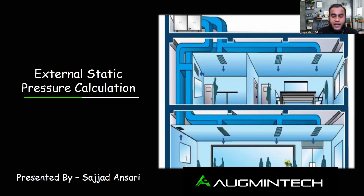Inside the AHU or FCU, we have a fan to supply the conditioned air to each and every area, in the return side also, and sometimes both sides. To find out the fan capacity, we need to submit the external static pressure details.